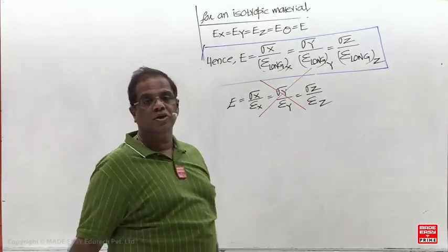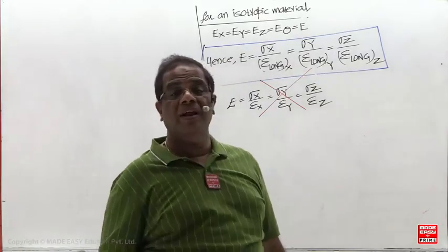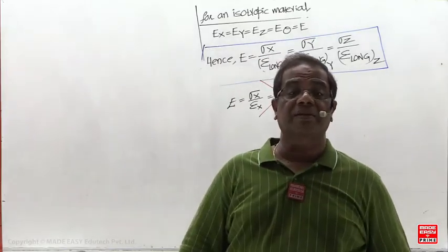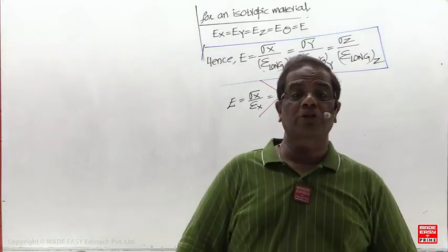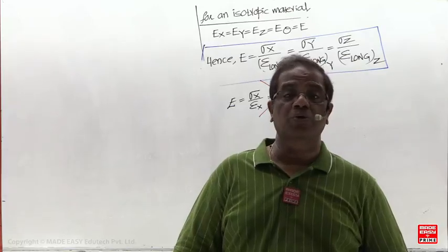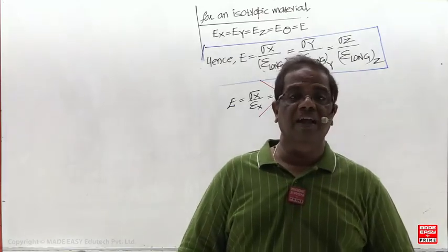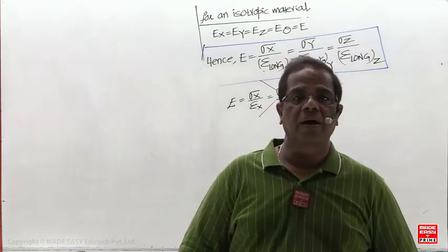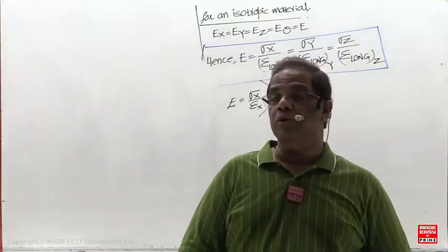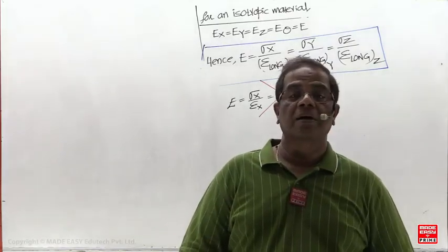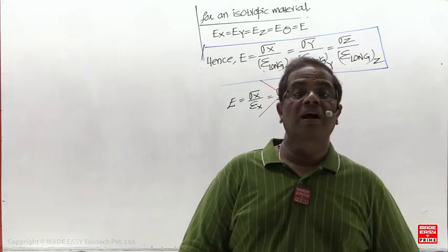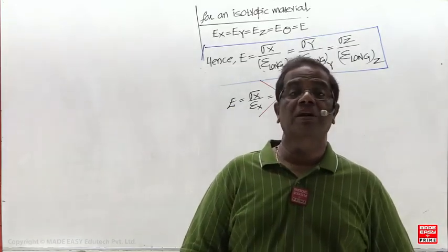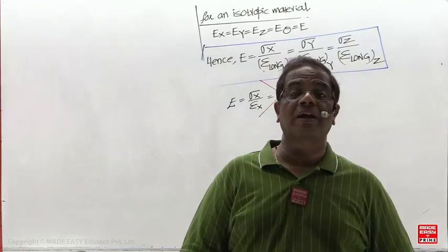This was not my question. I have given only the Young's modulus definition in the class: under a uniaxial state of stress, up to the proportional limit, it is the ratio of normal stress to longitudinal strain. About ten years back, one of my friends appeared in a BARC interview, and this question was asked. He mentioned that the definition is not valid under triaxial stress.